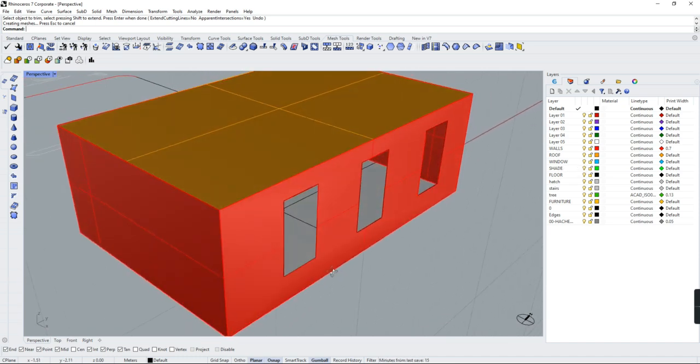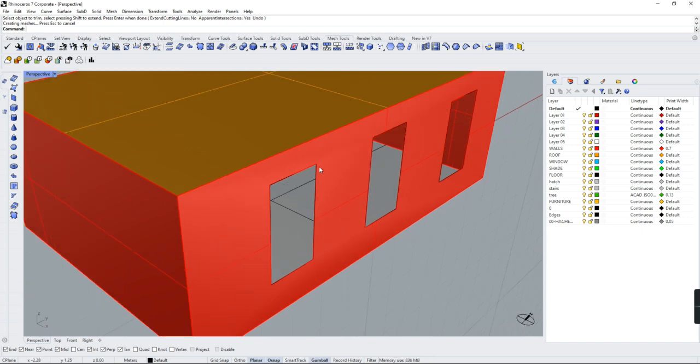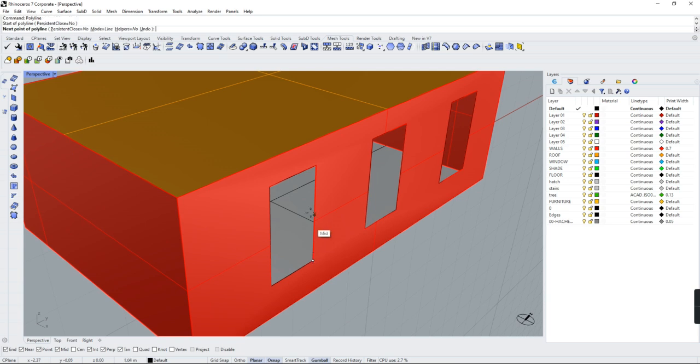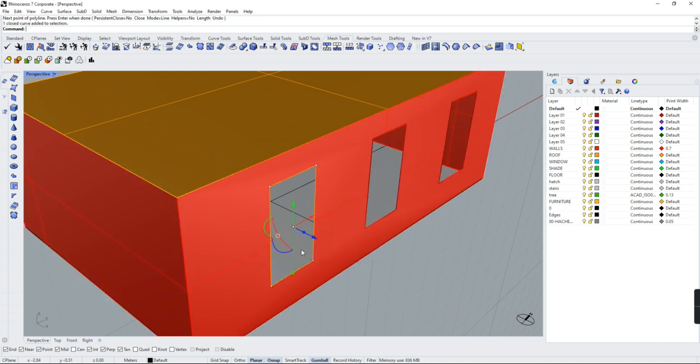The next thing we can do is have these probably polylines, or any way you can draw some sort of a shading device. I'm going to make an inverted U-shaped curve. Once I have that, I'll actually delete the older one. Just make a polyline here, here, here, and I'm done.